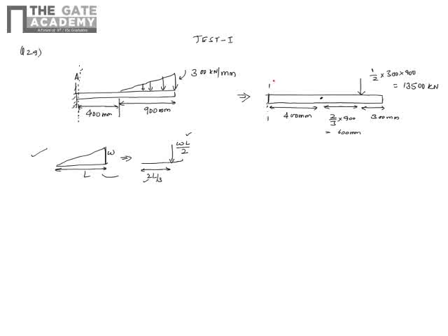Now it produces maximum bending moment at point A. So the moment that is produced by this load is basically that load into the distance from A. Okay, and that distance, so this is the moment produced by P. So when you want to find out bending moment at this cross section, all the loads to the right side of that will play a role.